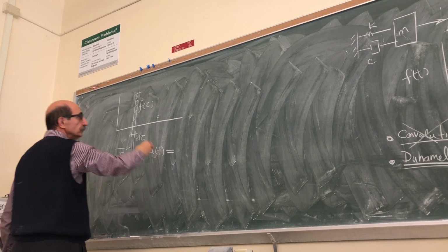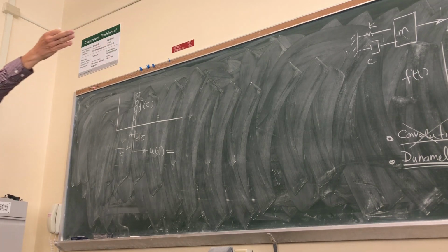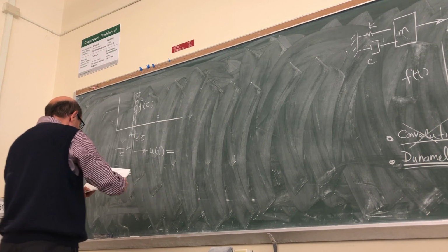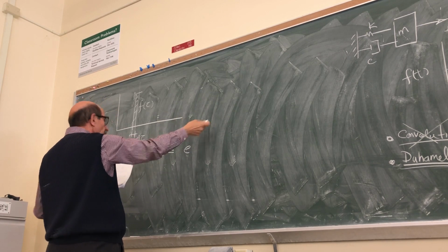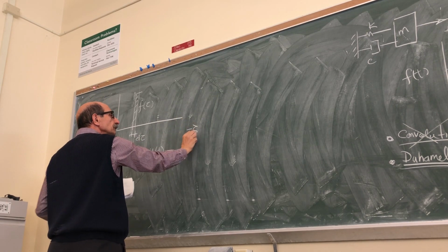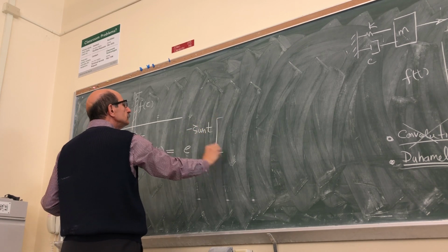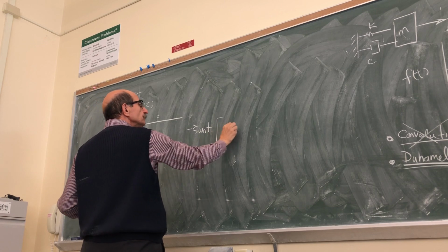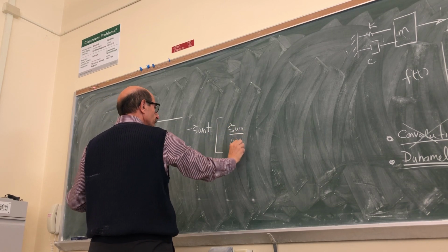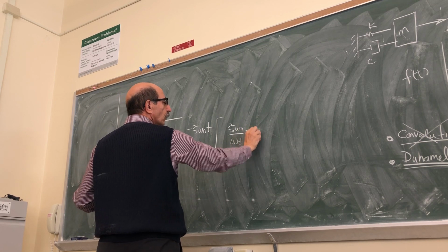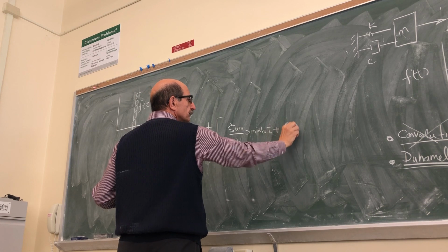It's a free vibration due to that initial condition being just the initial velocity. In general, this was the form. If you had a damped system, the steady state response of that system due to initial conditions was this form. If you go back to your notes, you will find that way back.